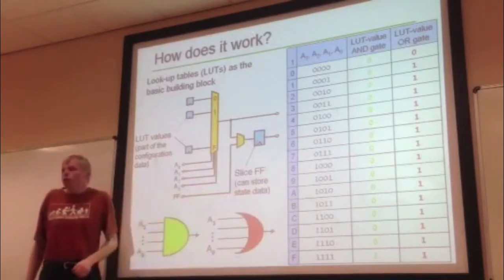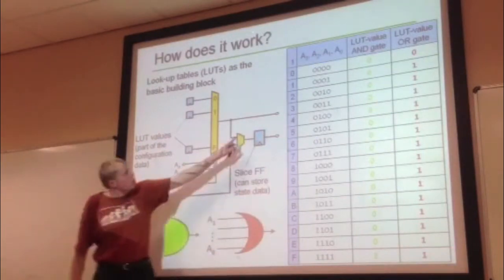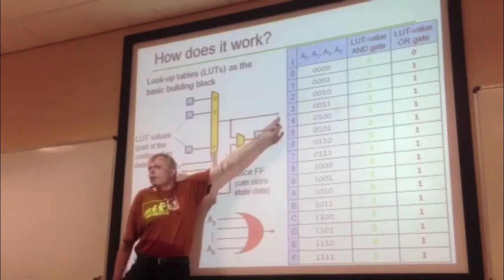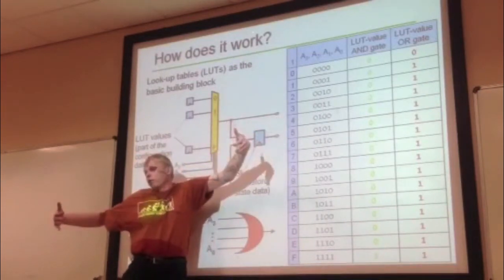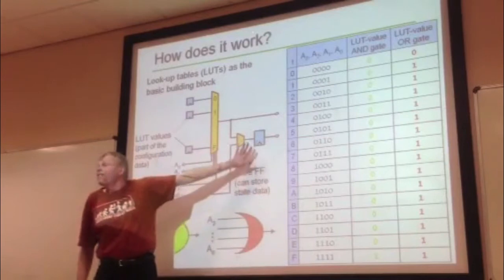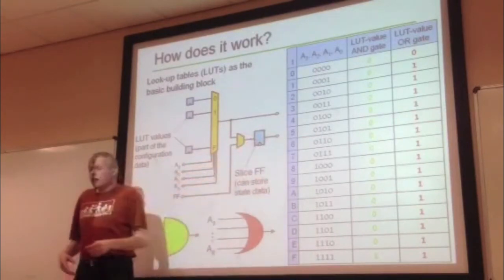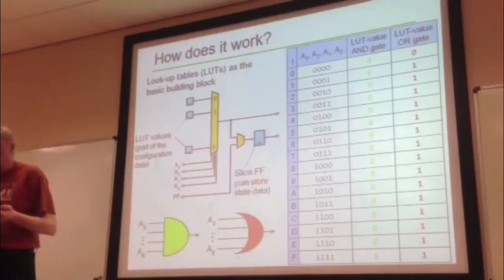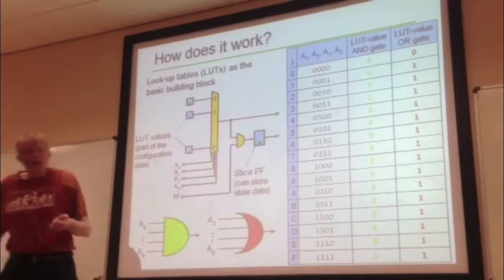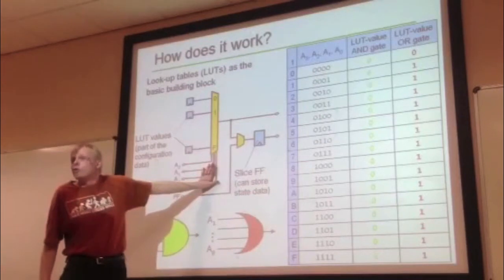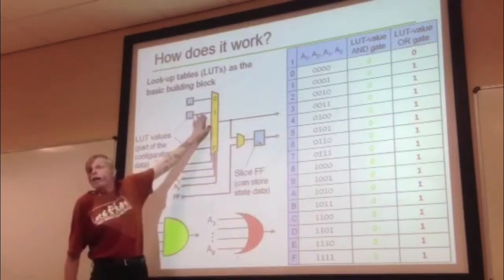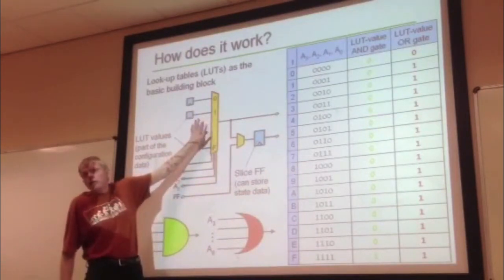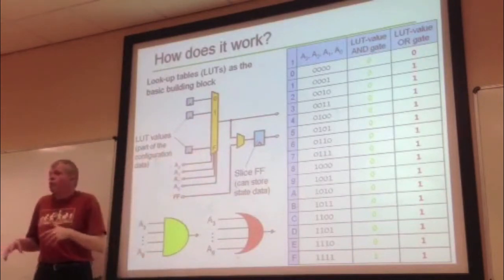And if the 4 inputs aren't sufficient, no problem. You can go to the next lookup table and build a bigger piece of logic. And you don't see these things. This is just like when you write code and it requires a certain amount of memory later. Here it is how much logic you consume, and you just count how many lookup tables, for example, are used. But it's not that you implement lookup tables directly.